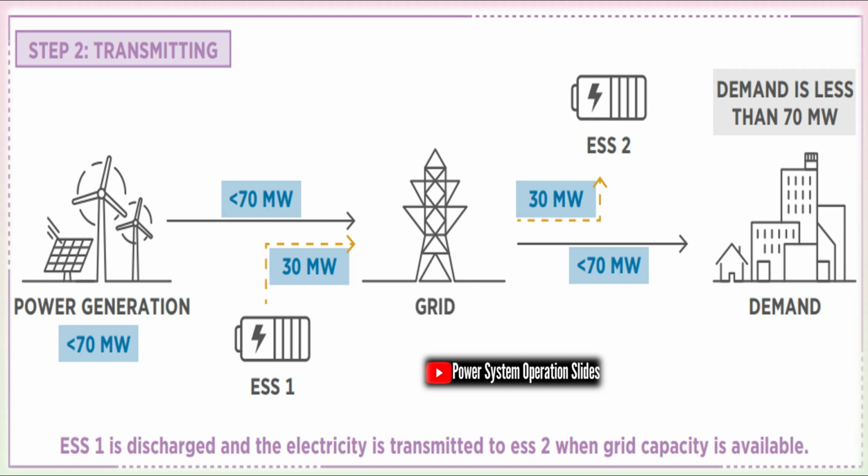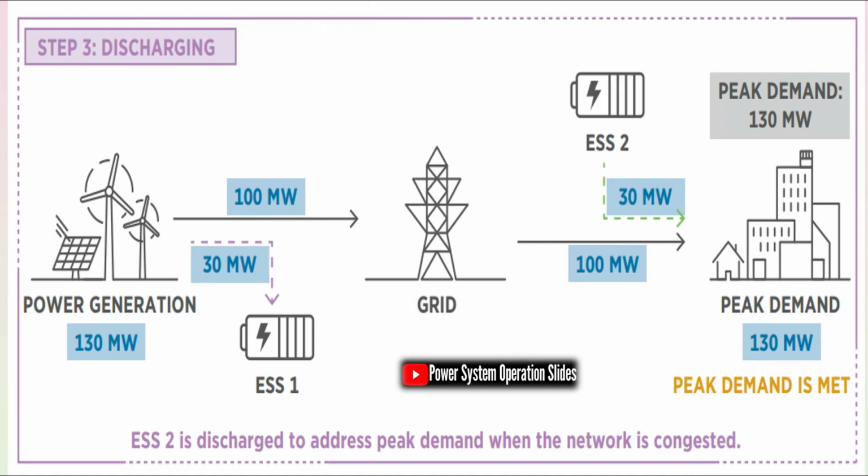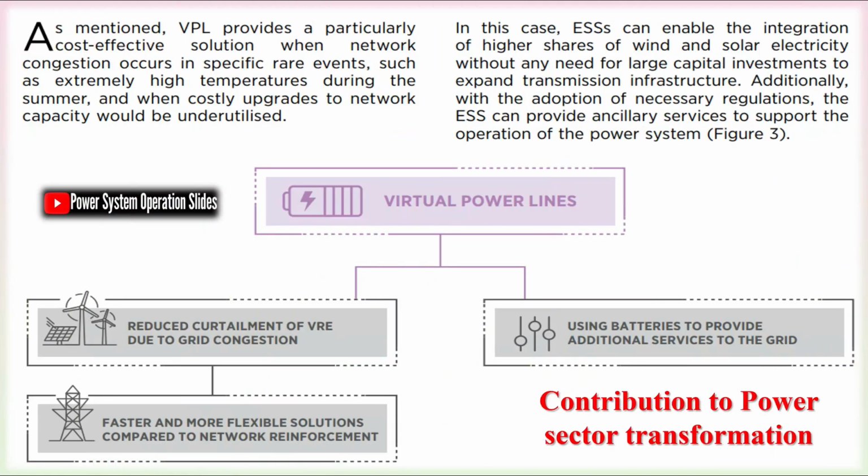Choose enabling technologies and communications architecture. Prototyping and simulation: build detailed dynamic and steady-state models, EMTP, RMS and OPF, and test coordinated control strategies under contingencies. Procurement and installation: deploy PMUs, upgrade communications, install hardware such as FACTS and BESS where required, and integrate EMS modules. Testing and commissioning: hardware-in-the-loop tests, staged commissioning under supervision, protection coordination, cybersecurity testing.